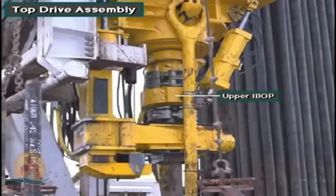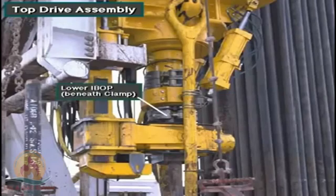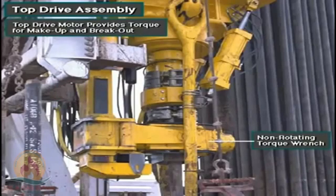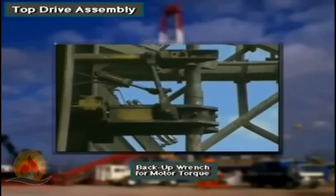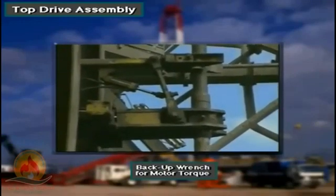The top drive unit also includes a pipe handler assembly that has an upper inside blowout preventer, IBOP, a lower IBOP, and a torque wrench. The torque wrench makes up or connects and breaks out or disconnects joints of drill pipe.